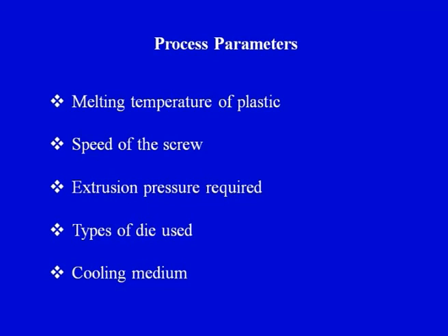Now, how much pressure the screw feeder should apply on the molten plastic is very important. So, the extrusion pressure required to form the shape of the final product is also very important. The type of die used is also equally important. Last is the cooling medium.